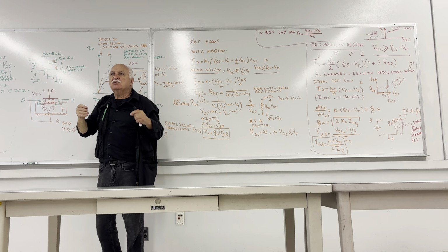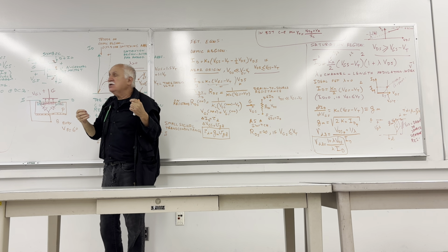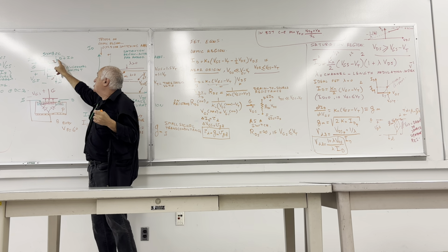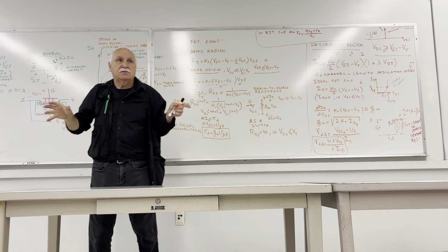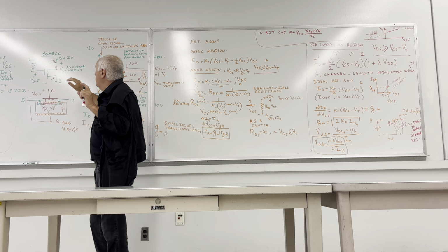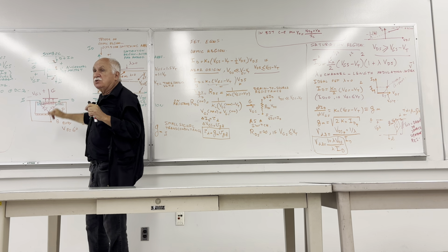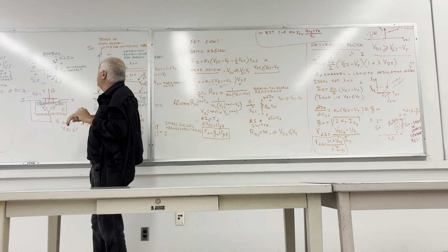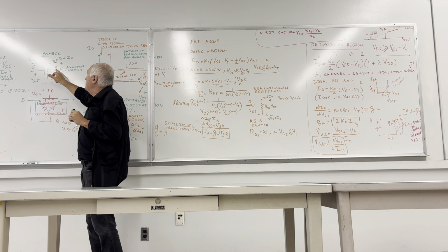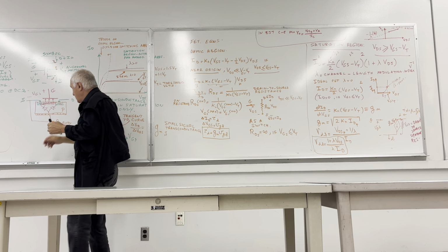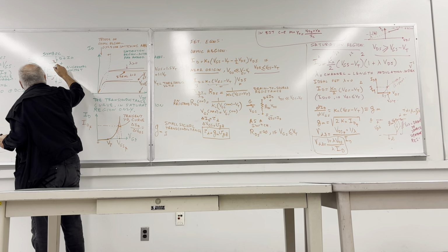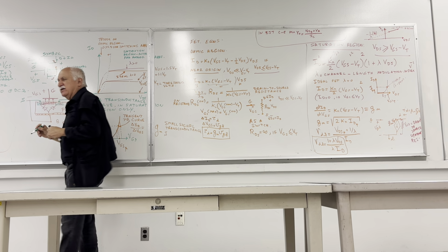But when it comes to analog operation, if we want to keep this as a drain all the time, in other words, if you want to make sure that this is not going to become negative with respect to the source, then you can join B into the S, and therefore people put a short right there. This is the model that I like.